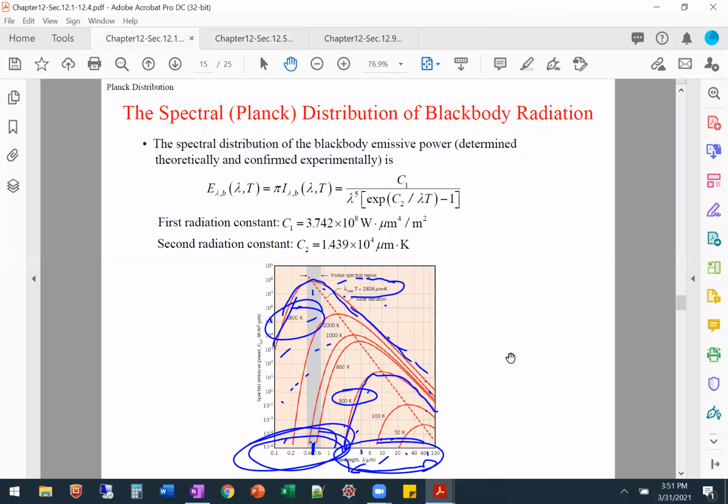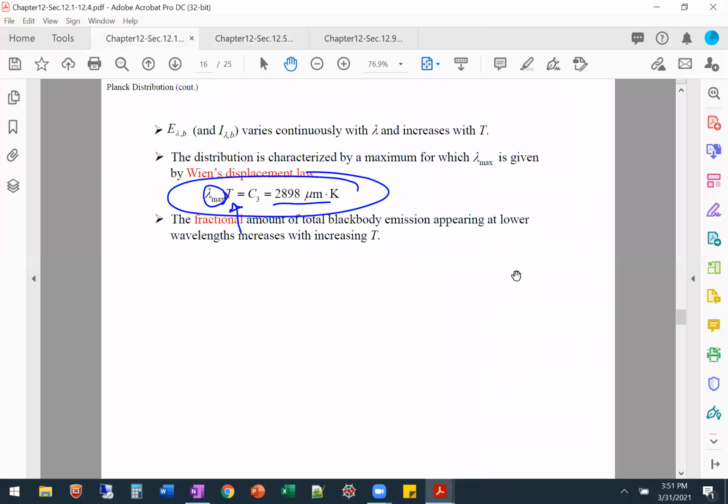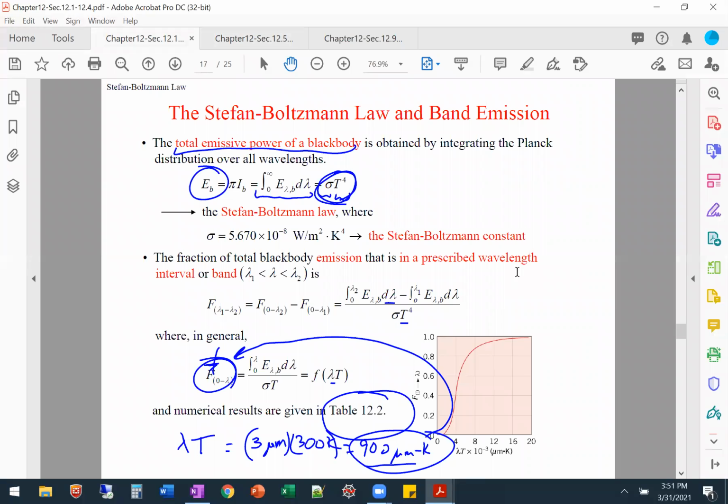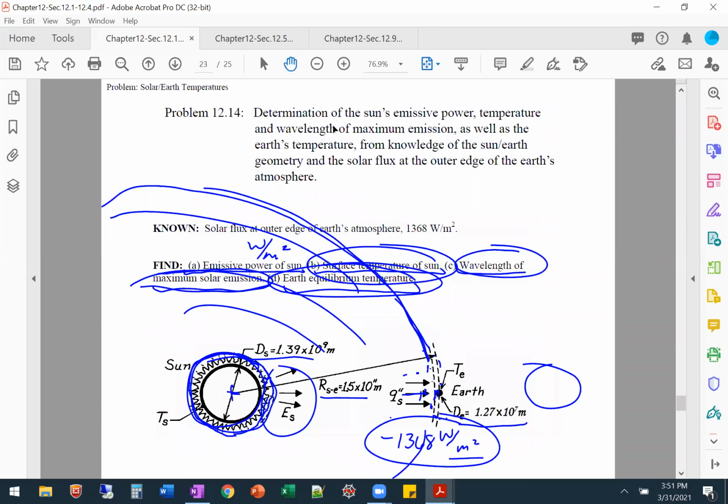I'm switching to that right now real quickly. Again, we're looking at that emission, because it's solar, it has this whole big emission portion right there, and we need to look at the fraction that's being emitted with the absorptivity of the material that we were given. And this is that fraction. We have F we can use, where we're looking at that integration over that wavelength over the total. Oh, it's on the other side of the slide.